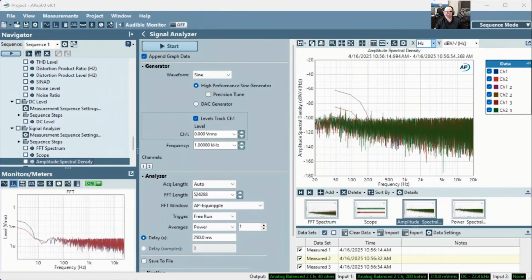So frequency response, there are a few different types of ways in which it might be measured, but fundamentally what's going on is we sweep a signal across the frequency range of interest while measuring the output level of the device and just plot that. There's nothing too fancy going on.